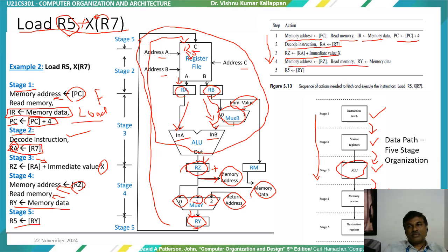After the arithmetic operation, move to the memory based on the instruction, or move it as per here. We are moving our answer to R5. So this is a very simple way of understanding how the register file, ALU, and the memory are correlated to execute the given instruction with respect to these 5 stages.